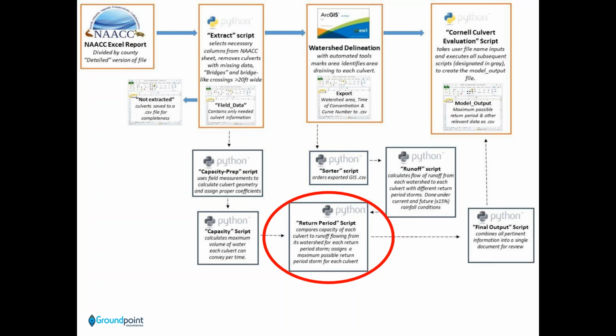Well, anyone that's ever done a GIS tutorial on how to do runoff modeling in GIS knows that the first thing you do when you download a DEM is you fill in all the sinks to get a depressionless DEM, because you want all your water to flow downhill, right? Which, if your scale of analysis is 1 to 24,000 and you're in rural Idaho or somewhere, that's fine. But not when you're dealing with local scale catchment delineation, roadside ditches, and culverts, particularly in built environments like a suburban or urban setting. And I'll show you some examples of that in a bit.